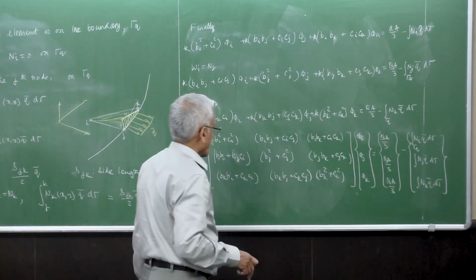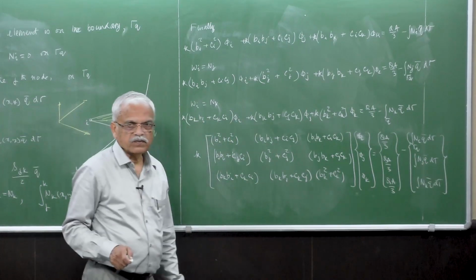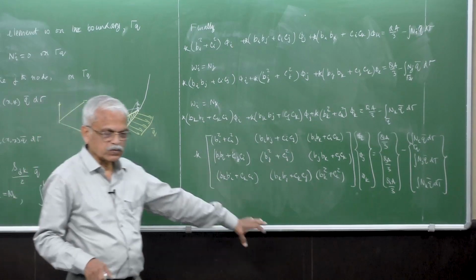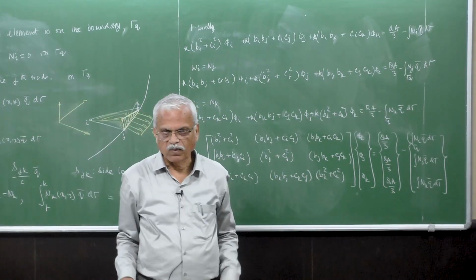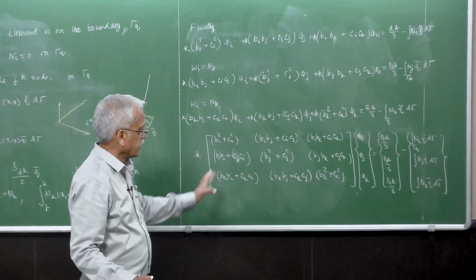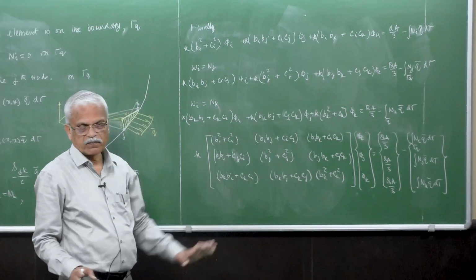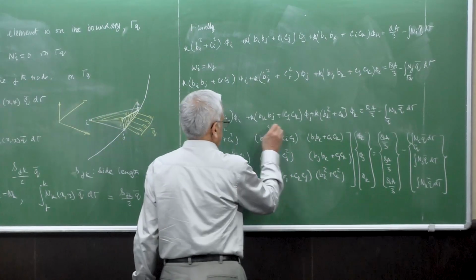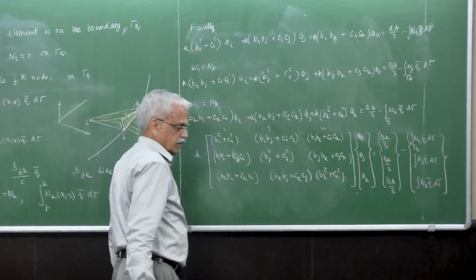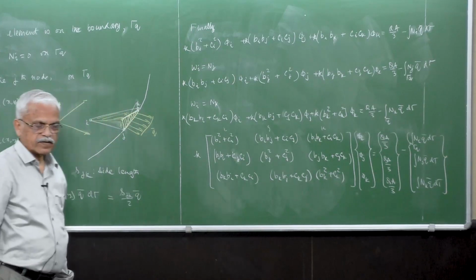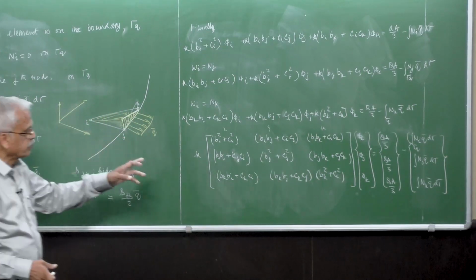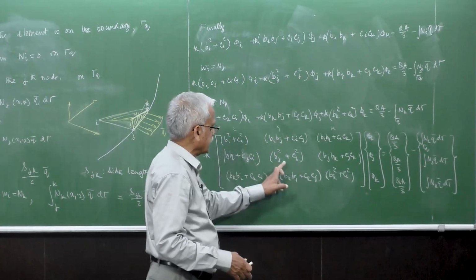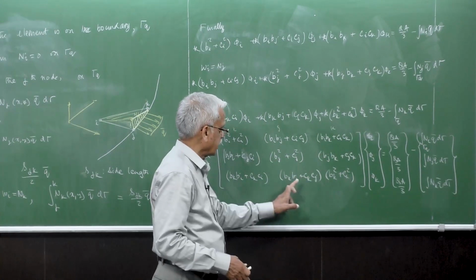Okay. So you also have to remember that this is the elemental equation, and to really solve the complete problem, it has to be assembled into the bigger system equation. So that means that these go to IJK nodes or IJK degrees of freedom, and that means that this is II, IJ, IK, this is JI, JJ, JK, and KI, KJ, KK.